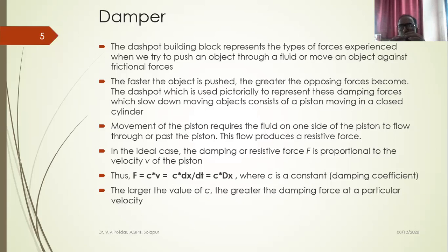So either I will have a damper proper, a shock absorber, where there is a cylinder, there is a piston and oil, so that motion will be retarded, isn't it? Slowed down because of flow of fluid across the piston and cylinder wall, isn't it? It damps the motion. It is the work of the damper.